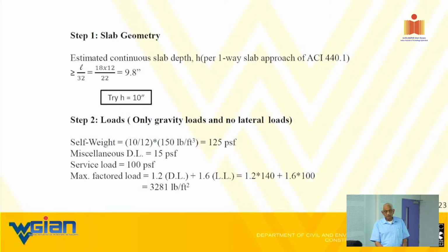Yes, sir. You see, or whatever those other kinds of loads you may have, utility loads and all those kinds of things. And we can neglect the wind load combination. You have no choice. You have to neglect that because you can only do this if you have a shear wall. If you have a shear wall, there is no wind load effect. Yes, because the wind load is taken by the shear wall.